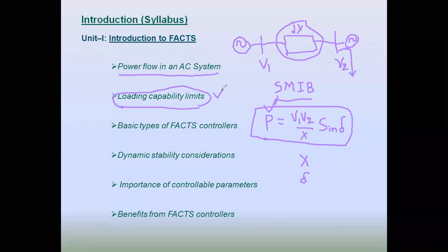In the case of thermal, particularly the physical, that is temperature, ambient temperature, and then ground clearance, and other factors will be there in the case of loading capacity. So transmission line capacity is mostly physical parameters: ground clearance, sag, distance between towers, and whatever it may be. That we consider, and of course the thermal, mainly temperature, ambient temperature, you are considering in the case of loading limits. In most of the cases we consider the temperature.